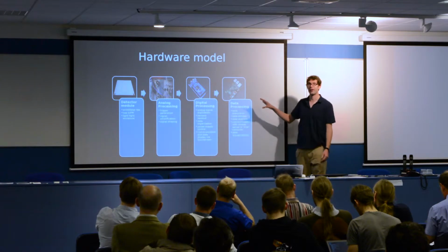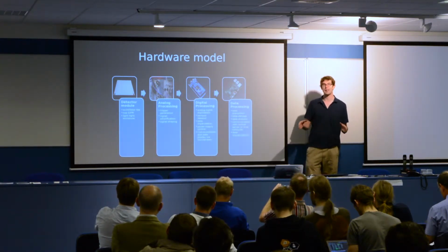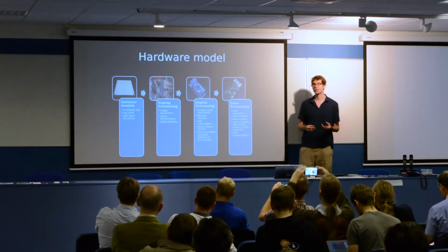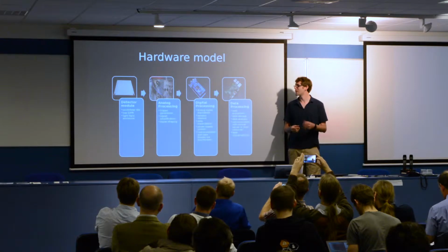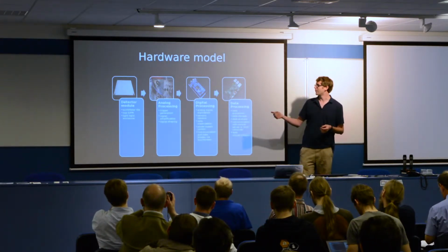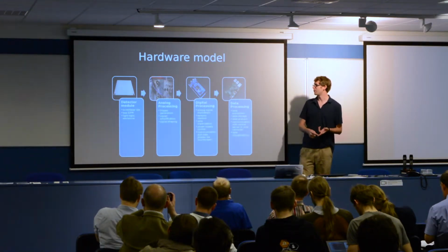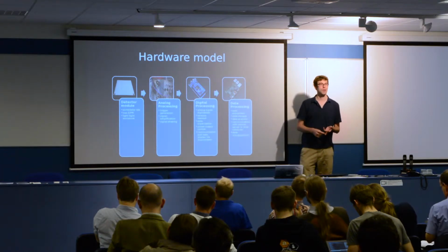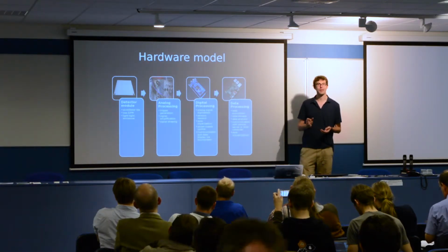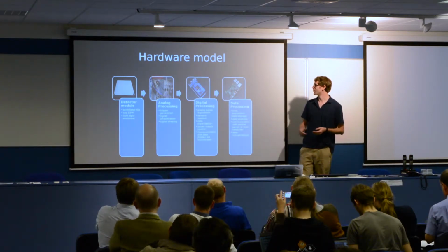This is the very high-level architecture that we have at the moment. We have a detector module, which is a scintillator tile. It's a piece of plastic with a special chemical additive. It has 2 silicon photomultipliers, which are the detectors, and we have to put that in a light-tight enclosure. We have a fair amount of analog processing, which is where we generate our trigger. We have our amplifiers, and we also shape the signal. The raw signal that we get out of the silicon photomultiplier is about 5 nanoseconds, so we have to lengthen that so that we can read it more easily.